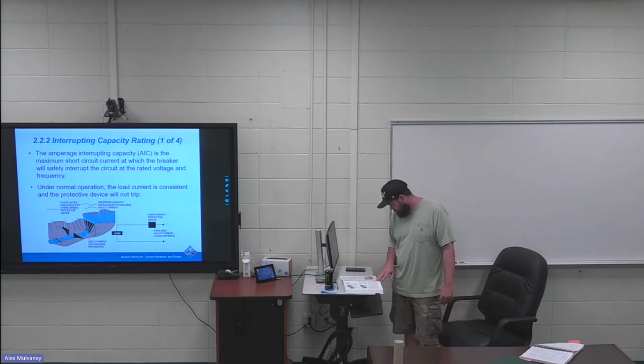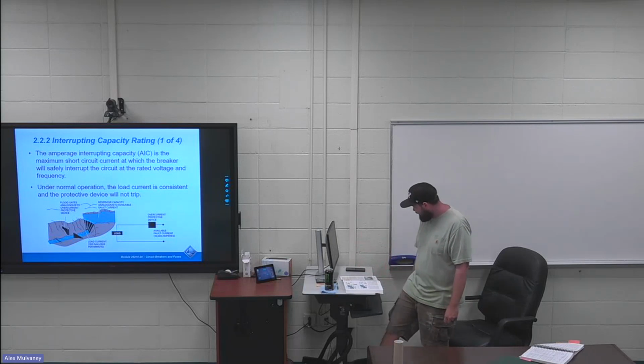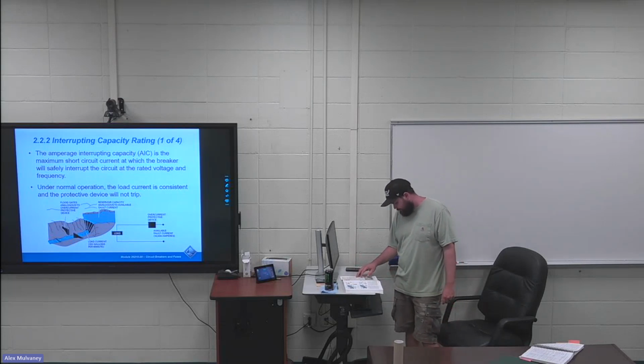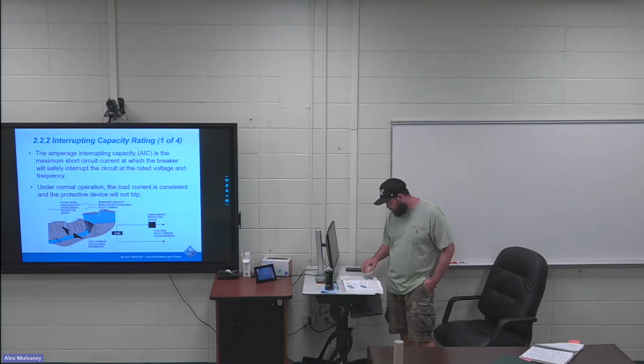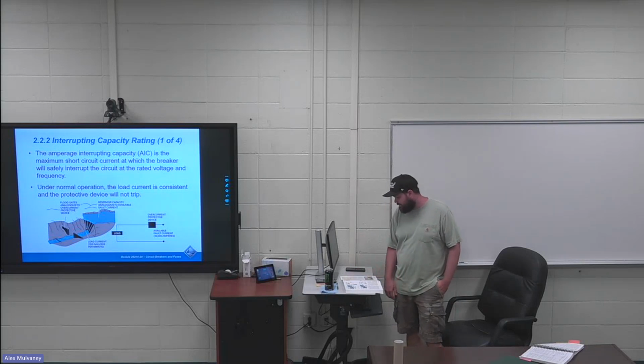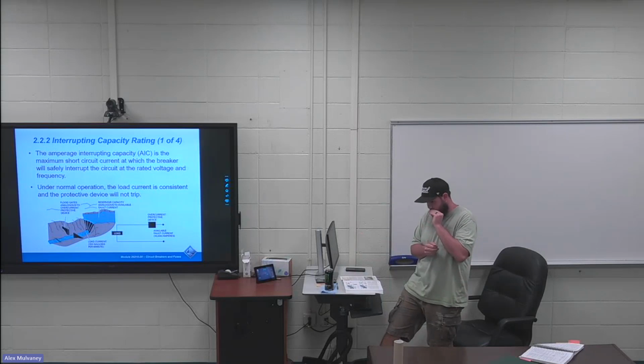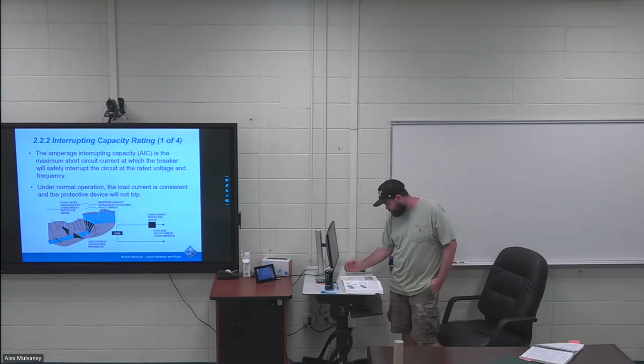Simple enough. I've got a couple more highlights that come out of those bullet points. So there's different categories of interrupting capacity. They have the standard interrupting capacity, the high interrupting capacity, and current limiting. And then details are listed in the 3 bullet points. In the first bullet point, I've got the sentence that splits the columns, still on page 9 highlighted. In residential applications, the available fault current is seldom higher than 10,000 amps or even near this. We don't get to 10,000 amps at our houses. It can be scary if we do.